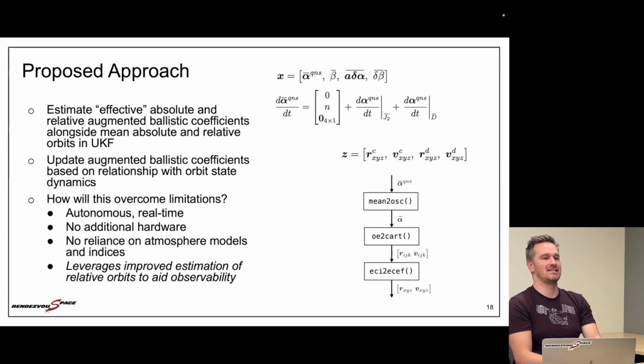we can't obtain the instantaneous acceleration that this spacecraft is experiencing due to drag, because that is something on the scale of micro or nano newtons. Instead, we're going to get this mean, call it an averaged augmented ballistic coefficient that a spacecraft will experience over time, which is truly what is needed for control, since drag-based maneuvers can take a very long time.